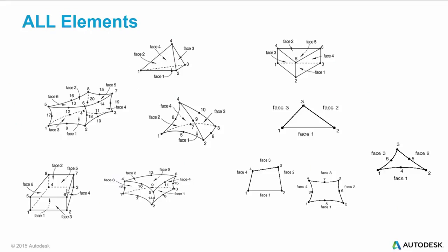If it can have map data over to it, we will map the data to it. So we revised the mapping scheme on the front end and the back end. And now the front end will read in any structural model, and it will tell you if there's any elements that we don't support, such as spring elements, contact, rigid surfaces, whatever. And it'll display all the elements that you can map to, and we'll do that for you.